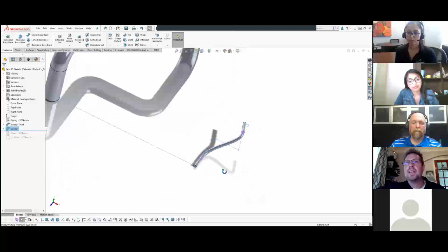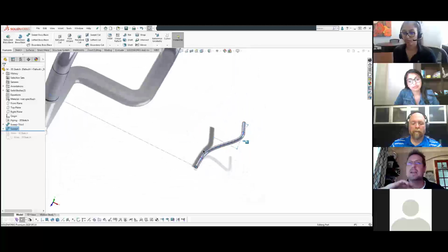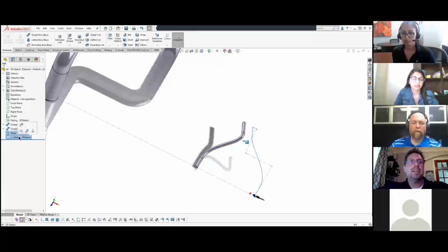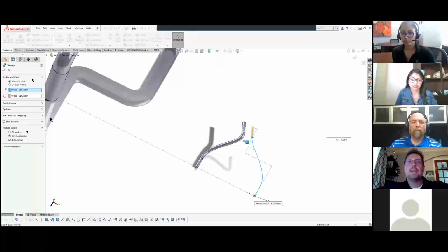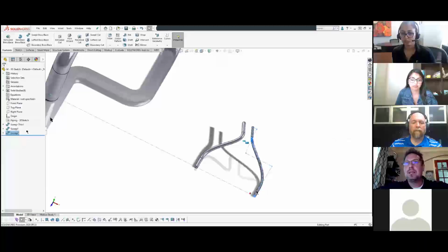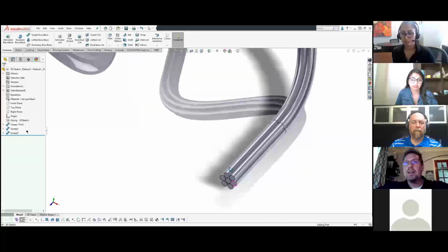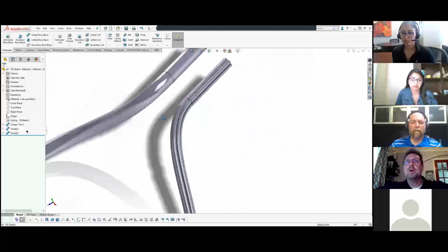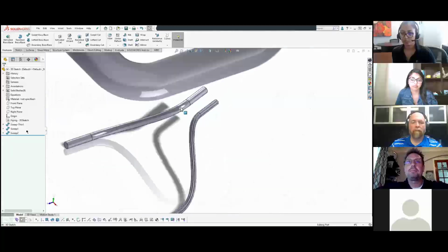When you do this, try and make a lot of tangent relationships so everything's nice and smooth as it contours around there. And then, so this would be, you know, you're doing piping, you could do tubing, and then maybe I want to pick on a 3D sketch and a 2D sketch, and we'll do, again, a swept boss or base. And I'll just say, okay. And this one's a little bit cooler looking because I've actually modeled in a bunch of little wires. So if you want to see what like a little cable might look like, then you can sweep all of those across a 3D path.